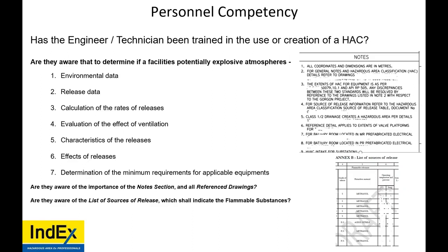There's environmental conditions, release data, calculations of release, ventilation characteristics, the evaluation of the effect of the ventilation, effects of a release, determination of minimum requirements for applicable equipment. Also, dispersion patterns. How will that gas turn into a liquid and disperse up or down?